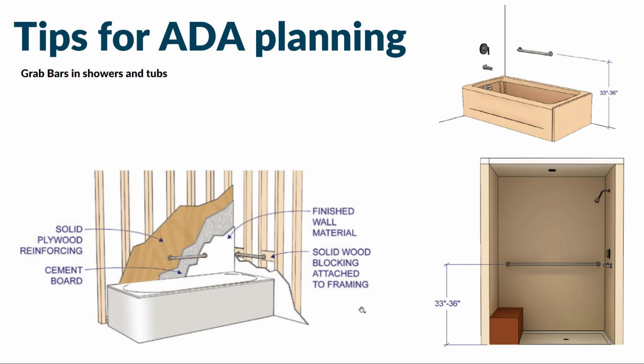And if we just think about that, and then you think about, oh okay, I'm going to put my tile up and put my grab bars in, those grab bars probably aren't going to land on those studs, right? And so if you just drill grab bars through maybe a tile wall, if somebody goes to grab one of those, they're going to rip them right out of the wall.